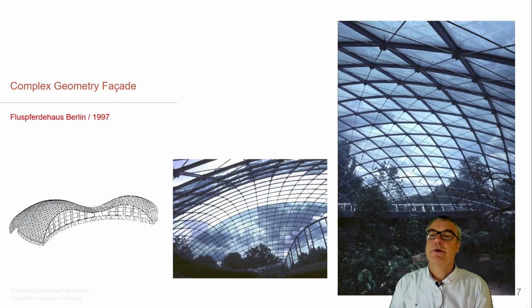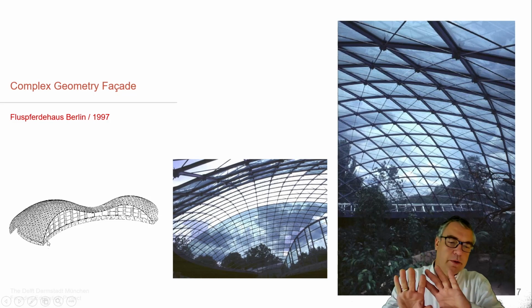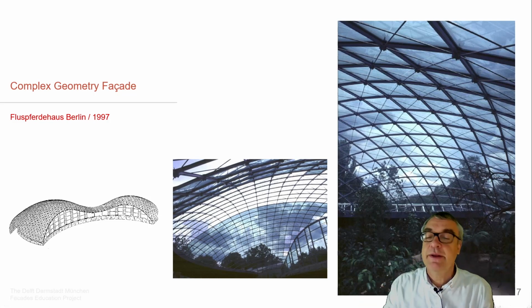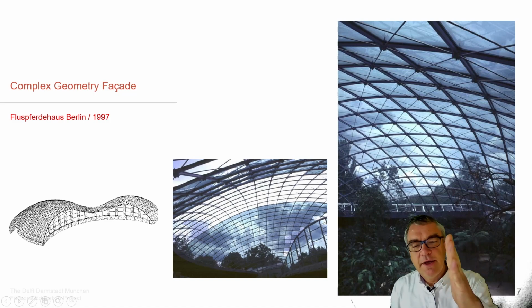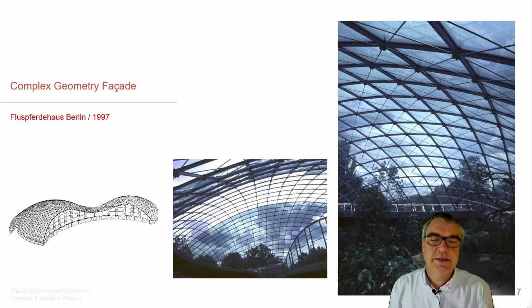When we continue with this one, another project in Berlin, which is a double shell structure with the synclastic and the anticlastic area, and then this shell, which would be entirely a structure, is cut off for aesthetic reasons for the entrance situation in here. Cut off means that the shell itself is cut. Penetrating a shell means you need to deal with additional forces in these situations.